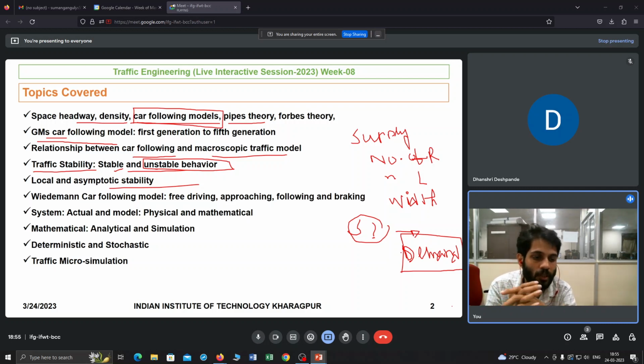So what do you mean by calibration? Suppose you have given input of 5000 vehicles, which usually in the field in 1 hour 5000 vehicles are crossing. But now you are seeing that only 4000 vehicles are passing along that simulation model. So now there is a deficiency of 1000 vehicles. So 1000 vehicles means if you calculate, the errors are very high, right?